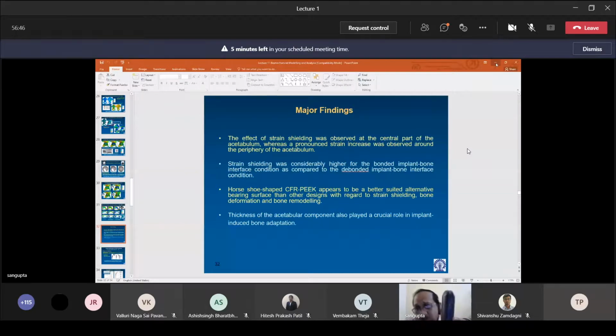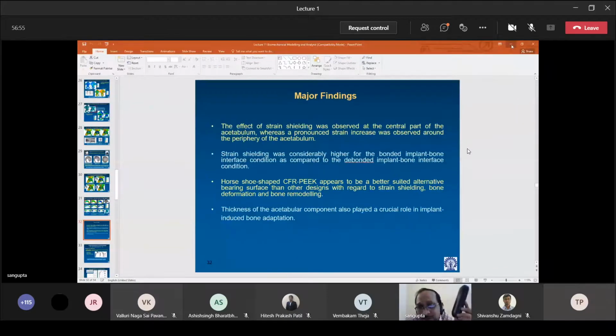Then you subsequently generate finite elements, and when we try to pick the CT gray value, when you place the finite element back to the CT scan data, you can easily make mistakes, because these elements would be generated outside the bone contours. And immediately you get very low values of CT numbers there, because it is already soft tissue or fat or water, and you get close to zero values.